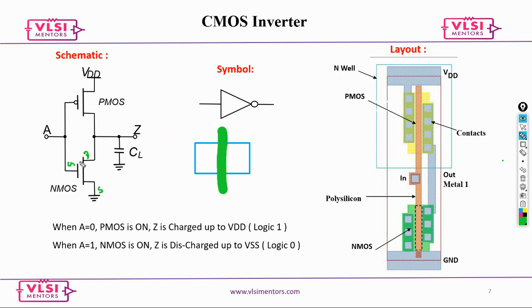Now your transistor, we need to convert it into a layout, and this is how it is going to be. This is something that we call the gate. Now you can pick, this can be source, and this can be drain. The beauty of your MOSFET is that the source and drain can be interchanged.